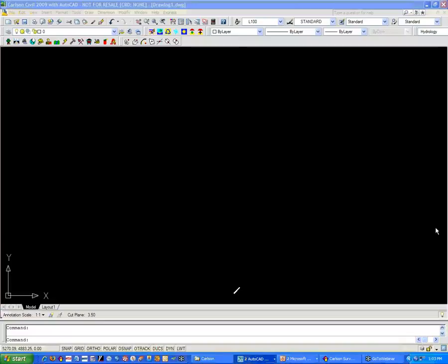Well, because I'm scaling the viewport, I could have one layout tab that shows my overall scale. The viewport scaled at 1:100, so it shows everything. The next layout tab, title block's exactly the same size, but the viewport scale is 1:50 because it's showing my plan and profile.